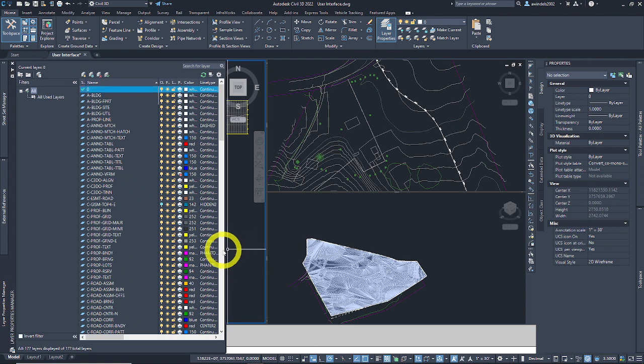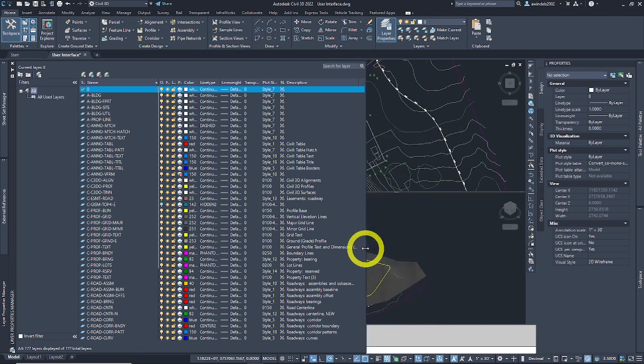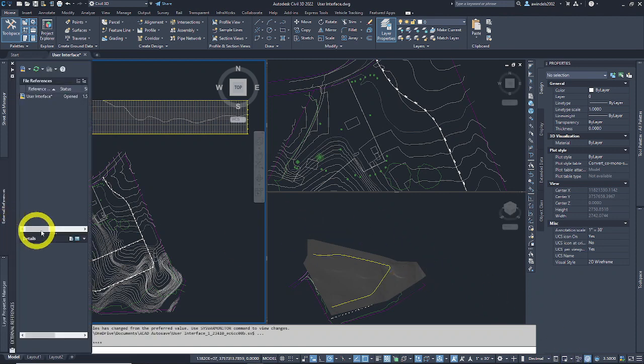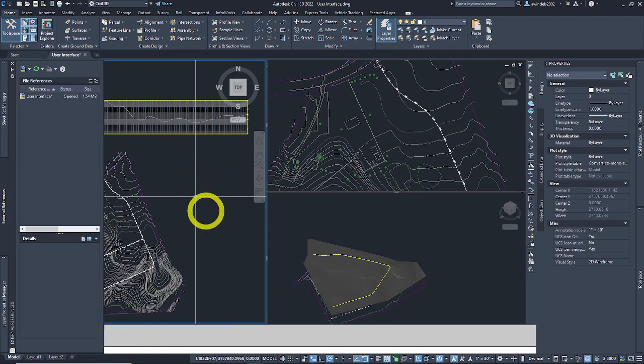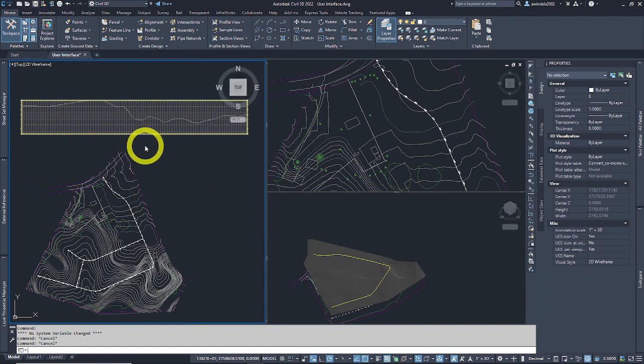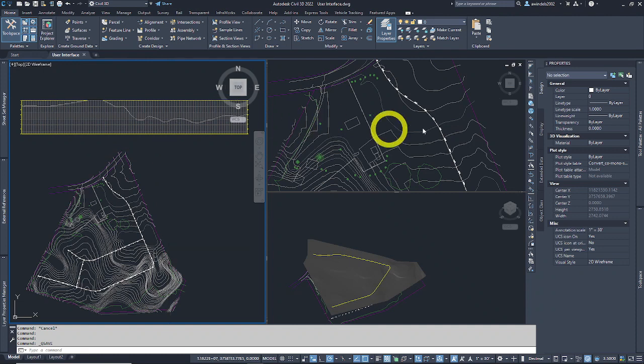So you can have Civil 3D. Actually, let's fix this layer dialog box, move it out a little bit. One thing I like to do is to lock my user interface right here, but I will leave it floating right now so I can still move stuff in my user interface around. Okay. And another thing to note about Civil 3D and AutoCAD in general, drawings will autosave, and you can save them when you want. They'll only autosave in this case every 10 minutes, but my settings, what I'm doing right now, doesn't save automatically. I need to close CAD out cleanly before it crashes inefficiently to save all the things I've just done in my user interface, so keep that in mind.